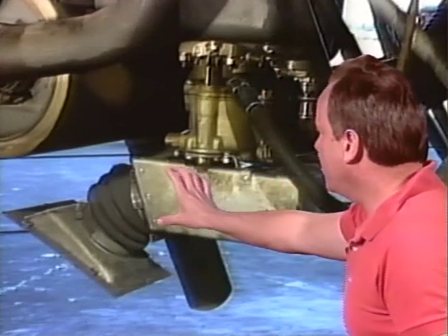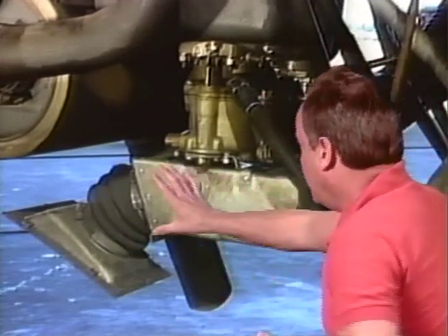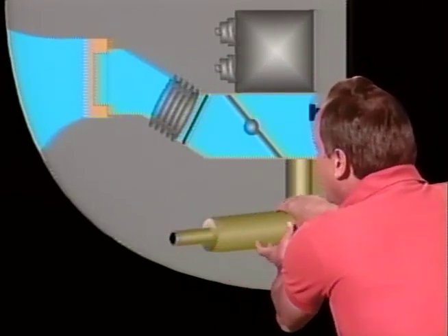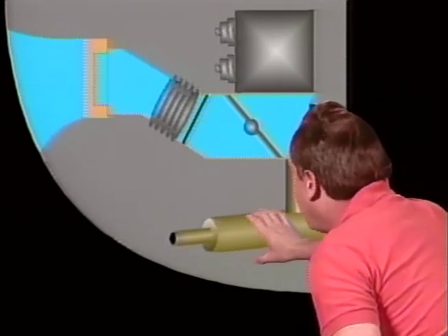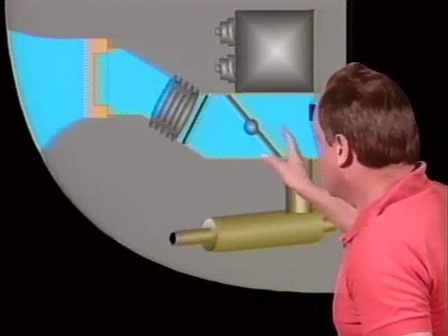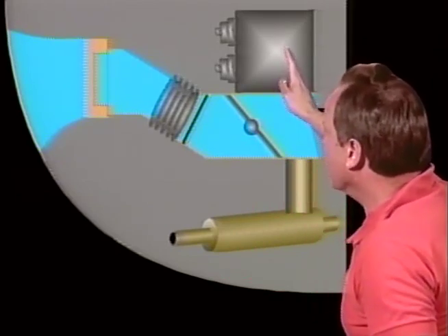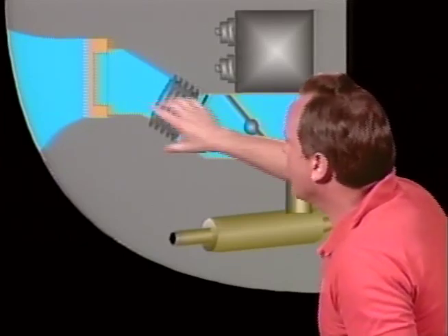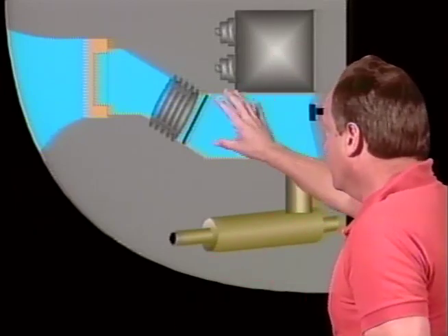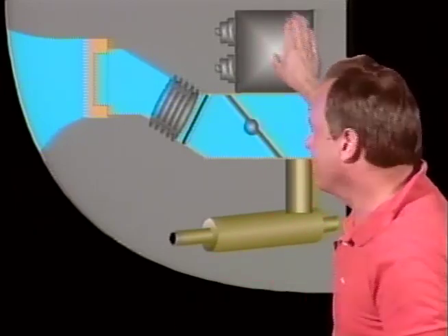They're also going to ask you about the carburetor air intake heater. And here we have one, basically the heat box, and it heats the air going into the carburetor. If we take a look at our drawing again, we'll get a little better look at that. You can see here we have the exhaust system and a muff around the exhaust system that circulates intake air past the exhaust system without mixing with the exhaust. And when you select carburetor heat, the carburetor is supplied unfiltered, heated air. On the other hand, if you don't select carburetor heat, then the air that gets supplied to the carburetor goes through this filter, but it's colder air. Of course, the reason you supply carburetor heat is to make sure you don't have icing inside the carburetor itself. This is supposed to be a carburetor up here, by the way, right up there.